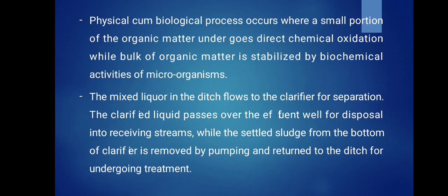The clarified liquid passes over the effluent weir for disposal into receiving streams, while the settled sludge from the bottom of the clarifier is removed by pumping and returned to the ditch for undergoing treatment. The remaining wastewater is again allowed to pass into the inlet of the oxidation ditch. This is the process.